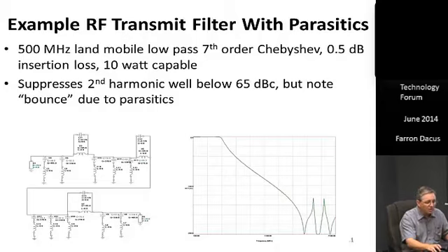But as we get out here where these parts start to go self-resonant, we see all these sawteeth form in the pattern. Instead of the transfer function continuing to go down, it reaches these minimums and then bounces up and down. And this is something to be aware of. Even in a very simple LC filter, you'll get this floor of attenuation of the filter. It doesn't just keep going down. So the bottom line there is you of course have to be aware of it and simulate it, and sometimes you need to use extra filter stages that you wouldn't have guessed going in because of that floor.